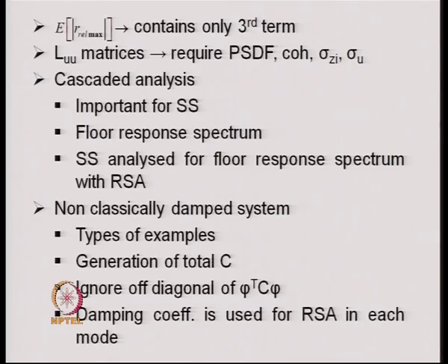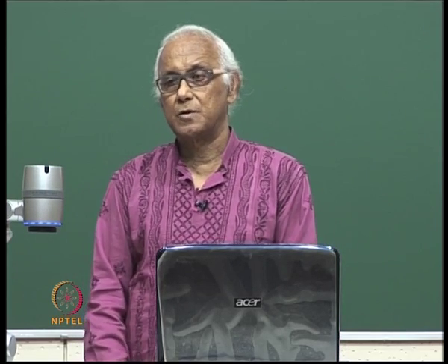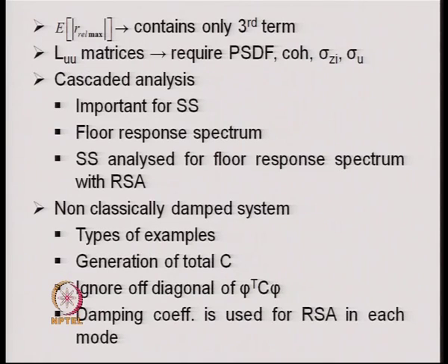After that, we discussed the basis of the seismic coefficient method of analysis, as it is quite popular with the earthquake engineering community, and it has been observed that the seismic coefficient method of analysis is essentially based on the first mode response. However, the mode shape of the first mode is approximated by different formulas, and the time period of the first mode is calculated by some empirical formula.